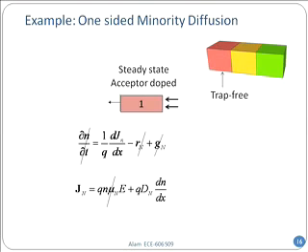So that gives you a clue that I want to know in general how the current flows. So that takes out. Electric field is again 0. I'll explain in a second. But this time the gradient is not 0. Why? Because from one side, from the yellow, carriers are coming in, so delta n is not 0. But on the left-hand side, in the metal contact, the concentration is 0. And so therefore, there is a concentration gradient.